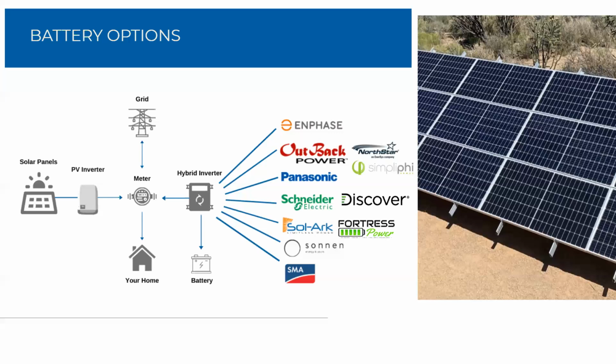It seems tedious, but it's very worthwhile so that the homeowner knows these loads are what will be on during an outage and what are contributing to the decline of my battery, so that they know what draws a lot. But again, air conditioners, well pumps, motors, and compressors of any kind are really going to be the biggest draws because they take a lot of power, more than anything else.